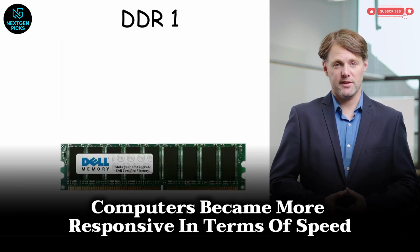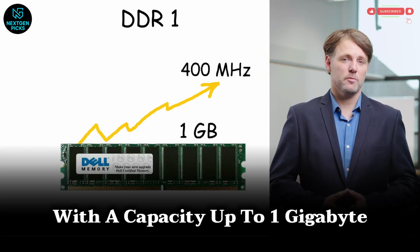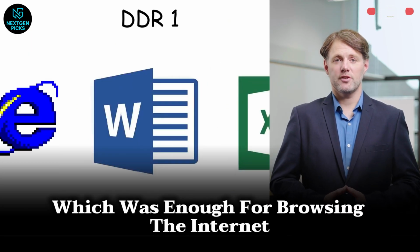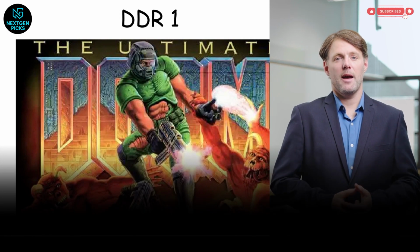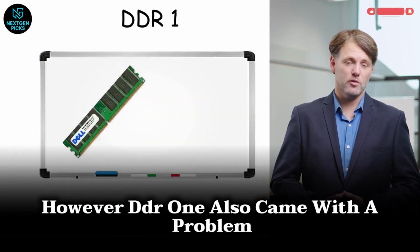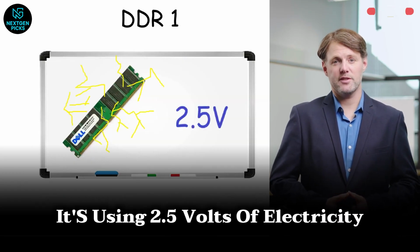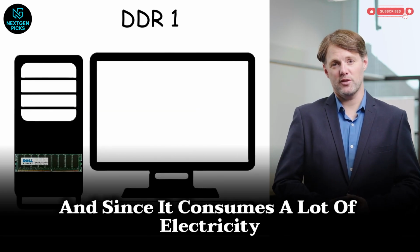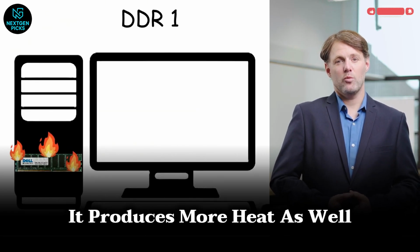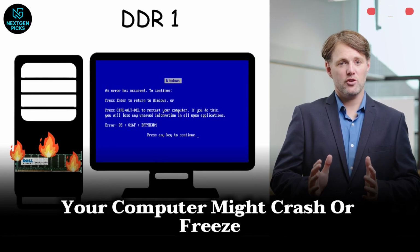In terms of speed, it runs up to 400 MHz with a capacity up to 1 GB, which was enough for browsing the internet, doing office work, and playing light games such as Doom. However, DDR1 also came with a problem. It's using 2.5 volts of electricity, which is a lot for RAM. And since it consumes a lot of electricity, it produces more heat as well. So when RAM becomes too hot, your computer might crash or freeze.